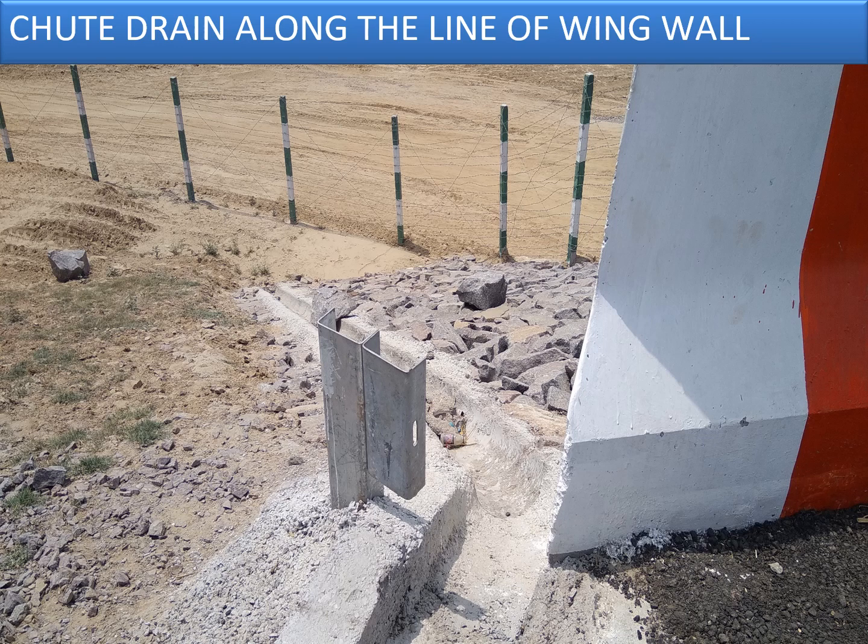So one has to make sure that the drains are along the line of the flow, not in the turning points. And if at all we want to have a turning like this, then the turn area needs to be properly closed with a complete circular pipe, so that there will not be any spillage of water out of this pipe. Because in this current scenario, the water will not turn as per the wish of the engineer who has made it, rather it will go straight and have an impact on the stone pitching which is being laid on the side slopes.